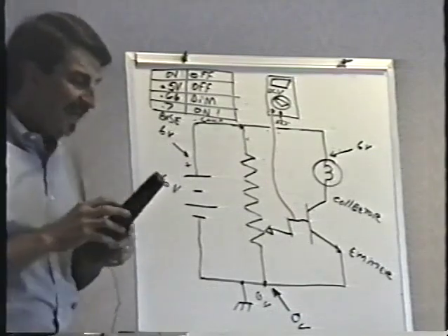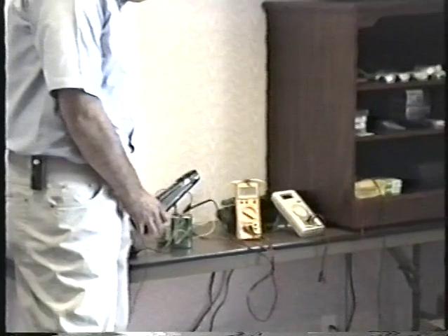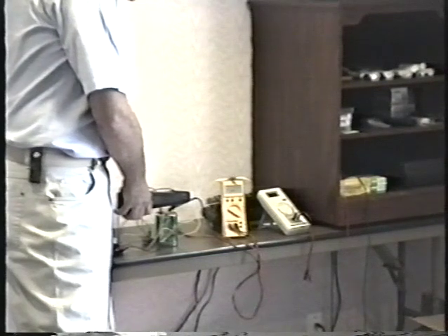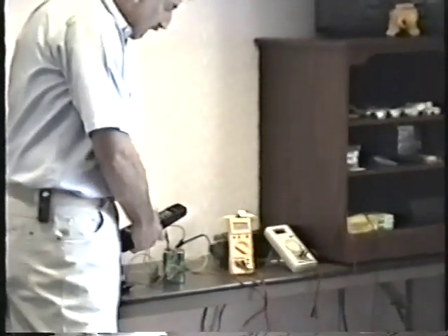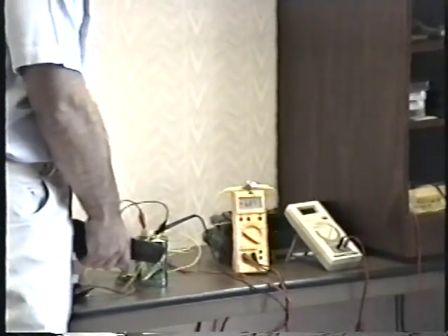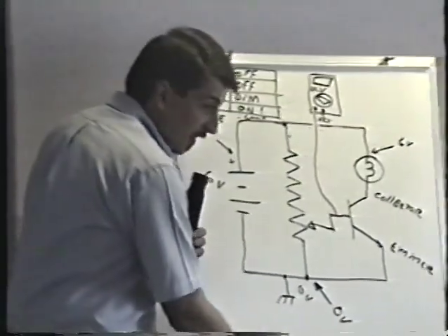So, in a way, when I said that a transistor is just a switch, I kind of lied to you, didn't I? Really, it is a switch in that we can make the transistor completely off, or completely on. But we can also put it anywhere in between, anything from completely off to completely on. It's continuously variable between completely off and completely on. So, in a way, a transistor is more than just a switch. It can also act like a variable resistor.